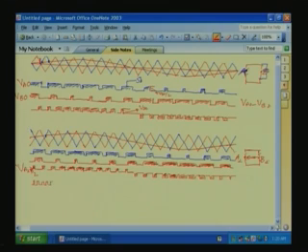But here, the transformer primary will be given sinusoidal voltages, and in this waveform all the individual harmonics will be dropped across the leakage inductance only.